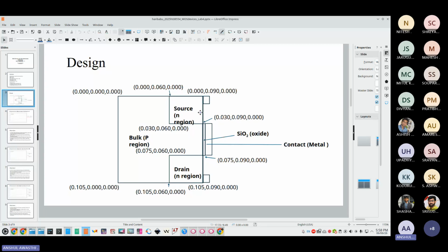In the normal course, the gate overlaps both source and drain. It slightly overlaps the source and drain region. So when it overlaps the source and drain region, there will also be capacitances, that is CGS and CGD, due to that gate. There will be CGB due to gate and body. Here will be the capacitance body to source, CSB, and here will be CDB. So there will be 1, 2, 3, 4, 5 such capacitances present inside the device. So this is a basic structure of a device.